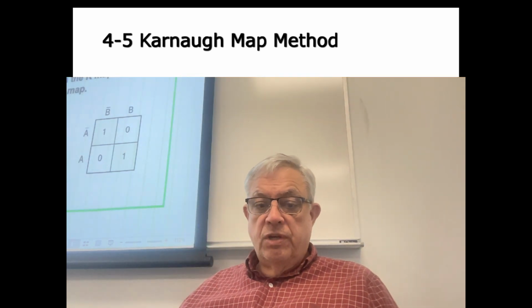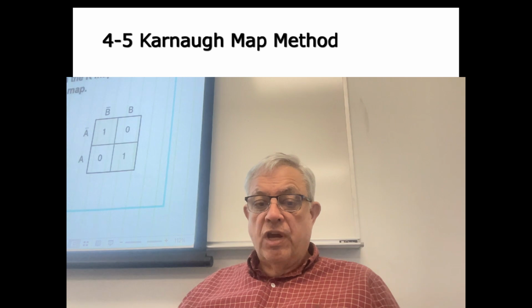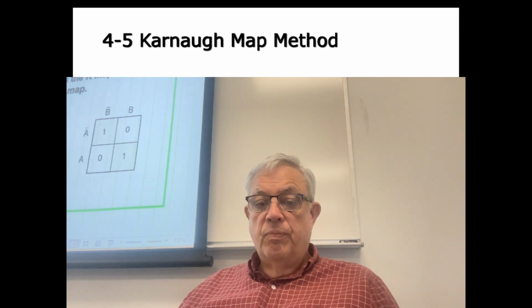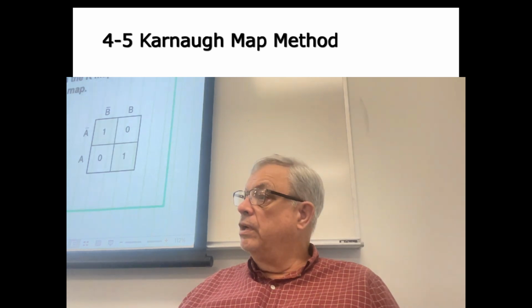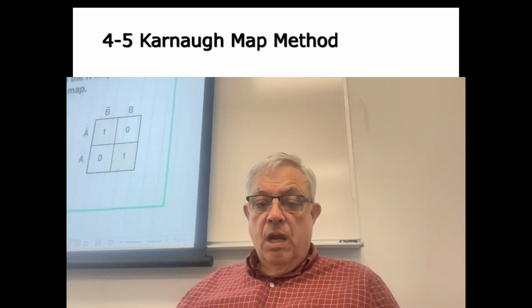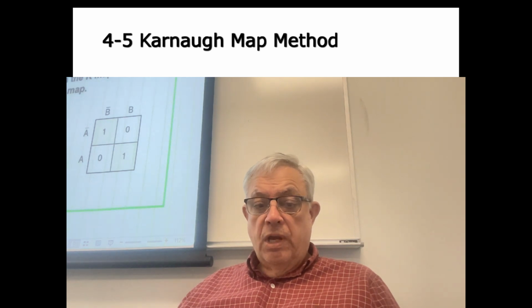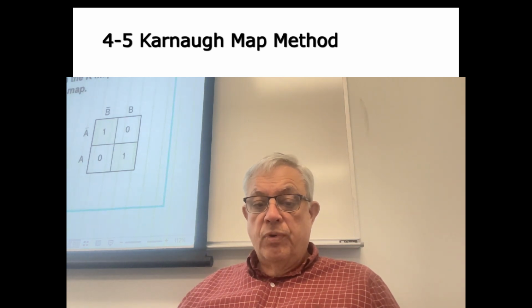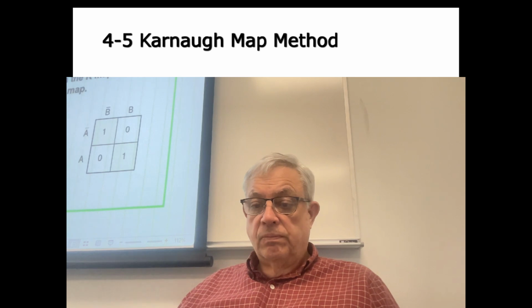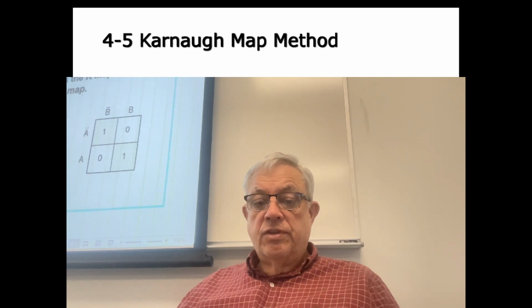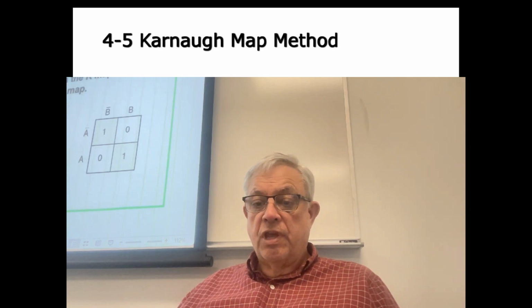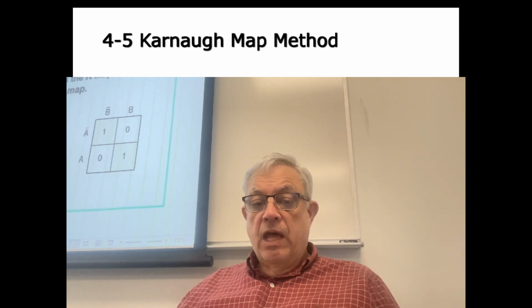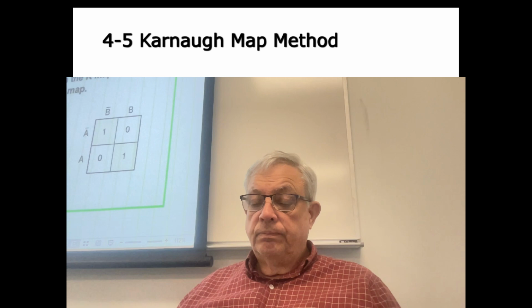If we look at this input and this output, if I know that A is 0, B is 0, but the output's a 1, then I've just calculated that the output is A not and B not. I look down here. If A is 1 and B is 1, then the output is AB. I take these terms on the truth table, and I know I've got 2 terms to deal with, A and B, and I've got both A and its complement.